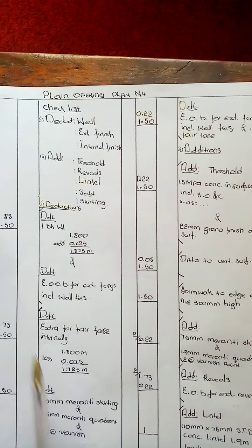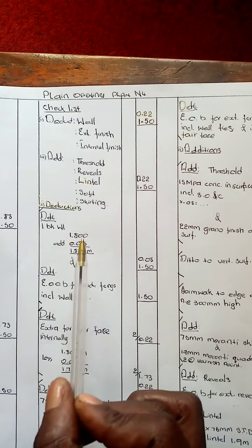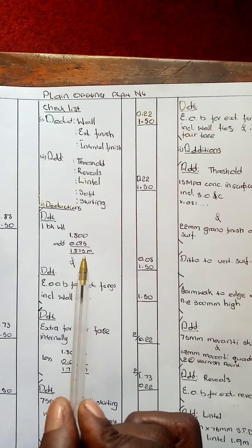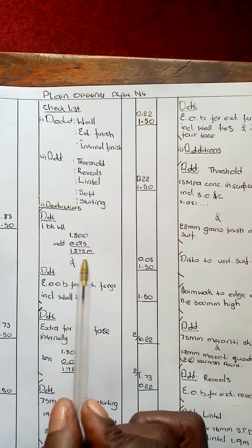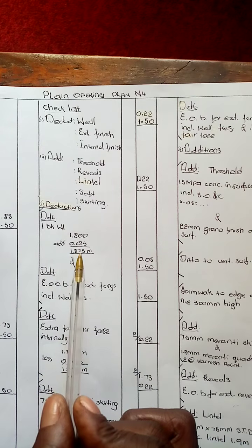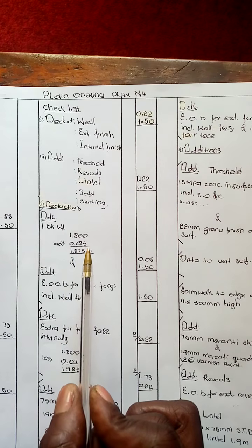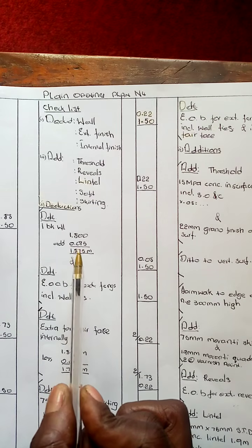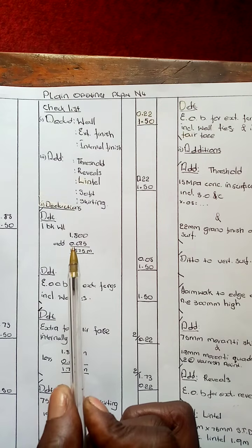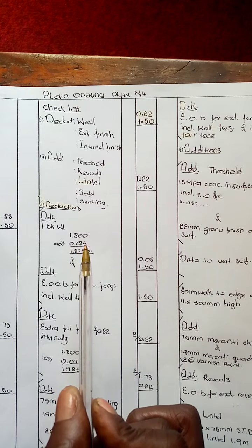We open our bracket. DDT, which means deduct one brick wall. The height of our brick wall is 1.8. Add 75 millimeters of that surface bed, the thickness of the surface bed, because this is what you are going to be deducting. The reason why you add that 75 is because you will have to add the threshold on that part of the building, right? So when you add 0.075 to 1.800, what we get